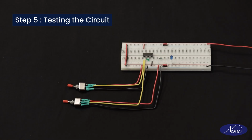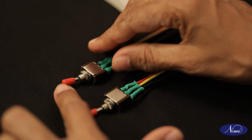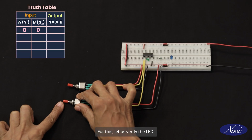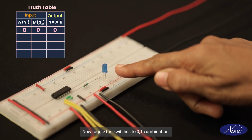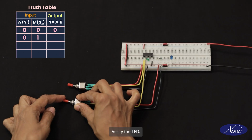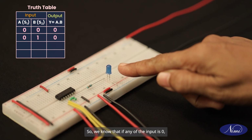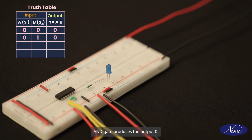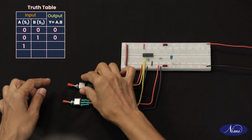Begin the test by operating switches S1 and S2. Check if the toggle switches S1 and S2 are in the low state. This indicates 0-0 combination. For this, let us verify the LED. It is not glowing. Now, toggle the switches to 0-1 combination. Verify the LED. It is still not glowing. So, we know that if any of the input is 0, AND gate produces the output 0. Now, toggle the switches to 1-0 combination.